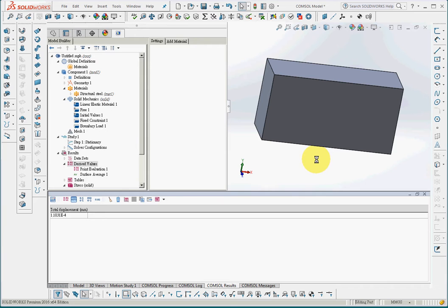And this lecture is very important because you must be familiar with the 6 parts of the structure of CAE analysis. The first part is the geometry, the second is the material, and the third is meshing, and the fourth is boundary condition and loading, and the fifth step will be running the procedure, and you get the sixth step, which is the result. And this is a structure that applies to any CAE softwares, including ANSYS, COMSOL, or Nastran, or Cosmos, or SolidWorks simulation.